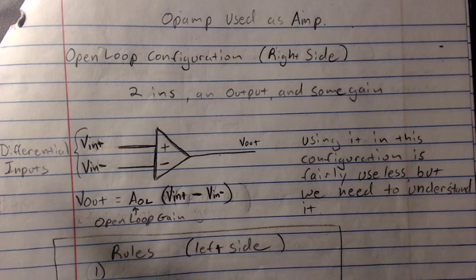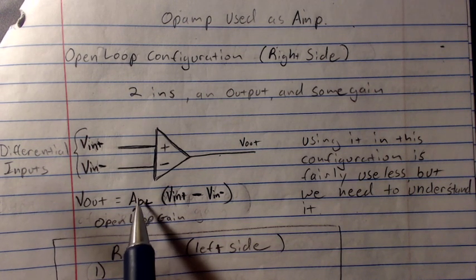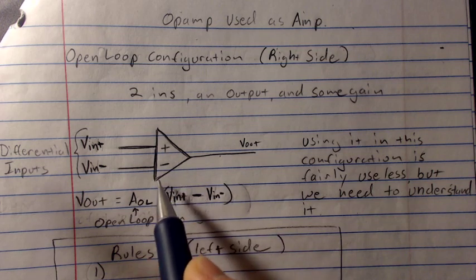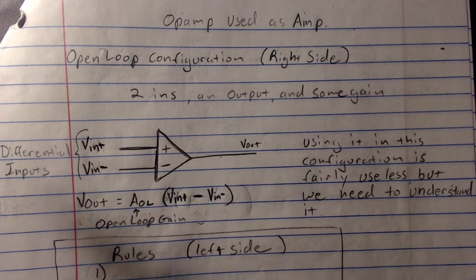It's really high. Sometimes you open up the data sheet for the part, like I'm going to use a 741, so I go ahead and open up the data sheet for it, and it tells me the open loop gain is going to be 100,000. As you'll see, it actually won't matter. What matters is the open loop gain, or the natural gain of this device with no feedback, is just a super large value.